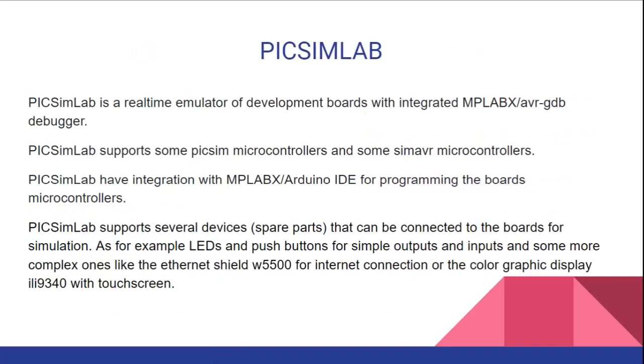Microprocessor has fewer registers, therefore most of the operations are memory based, whereas microcontroller has more registers, therefore a program is easier to write. The microprocessor has a zero status flag, whereas microcontroller has no zero flag. Microprocessor is mainly used in personal computers, whereas microcontrollers can be used in controlling systems such as washing machines, air conditioners, IoT devices, etc.